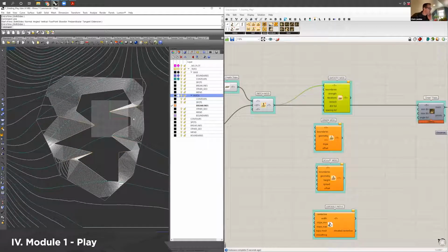And they say, you know what? Actually, this part is really fine for being kind of rigid. Why don't we just make the bottom part of it smooth? So what I can do is draw a polyline. I just typed PL, but you can type polyline to get a polyline. And I'm just going to have it be in this area here, kind of at the bottom of my